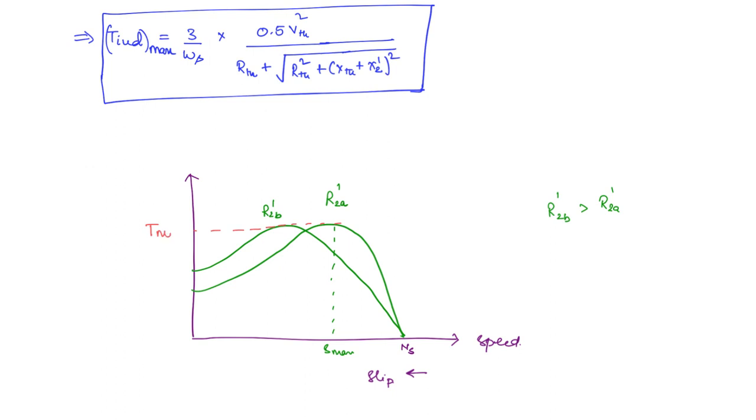This is the important point here. This is the torque axis. Further, if you increase the rotor resistance, the maximum torque is going to shift further here. So at one point, the maximum torque will become the starting torque. So this is how the torque characteristic is going to look like. R2C dash, if you take, is going to be higher than both the resistances.